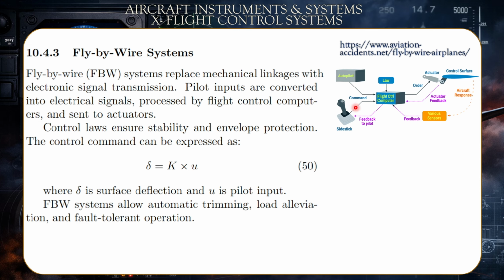So when he moves the handle, the very same movement should be replicated by the actuator, which receives a higher amplitude current, but the current would be the same value, like the same analogous signal, mechanical variation. The actuator would be moving the control surface. Actuators, by the way, convert electrical energy into mechanical energy, and the actuator itself would be controlling the surface instead of the pilot directly.